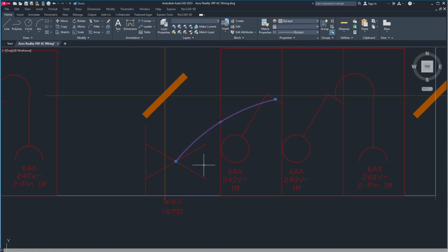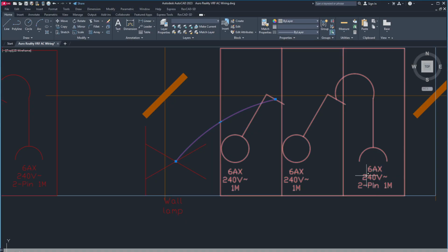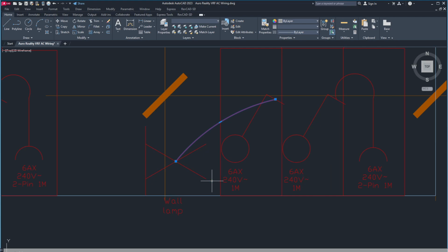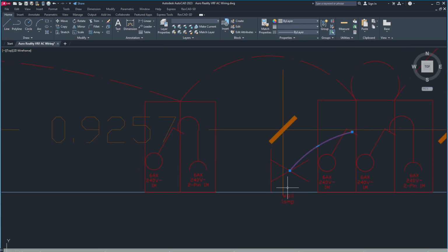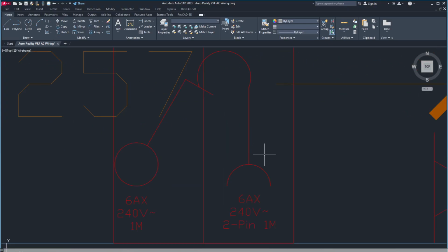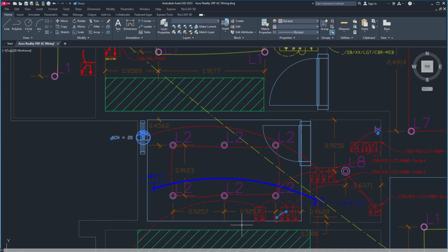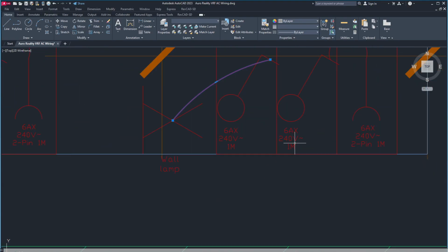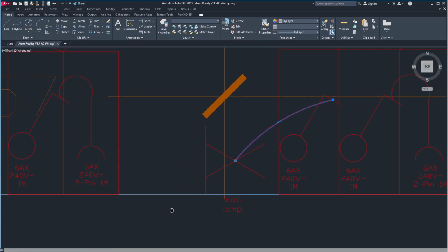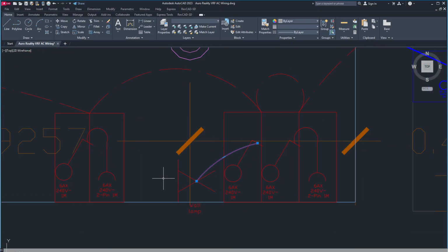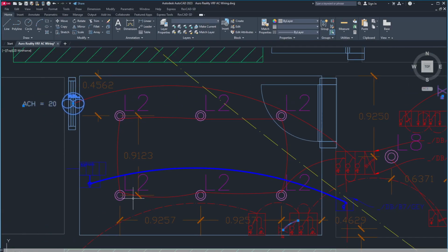Okay, switch number 1 operates the light, switch number 2 operates this socket. This is 2 pin, because in the bathroom 2 pin is more than sufficient for trimming, electric brushing. One more is provided here. Okay, and these boxes shall be placed at a distance of 2 feet away from the tap or the nearest tap position.